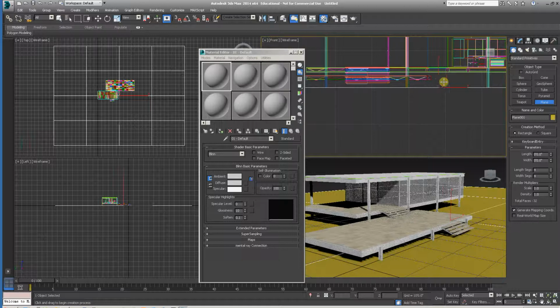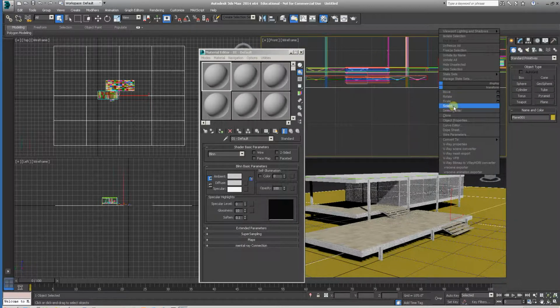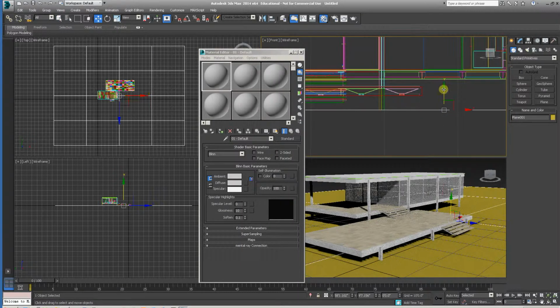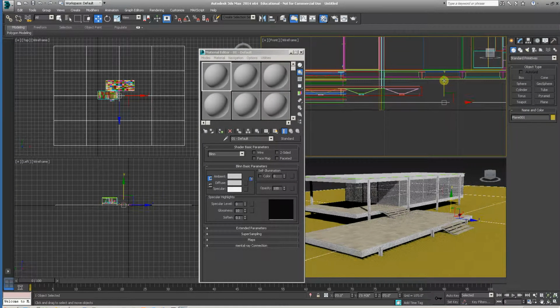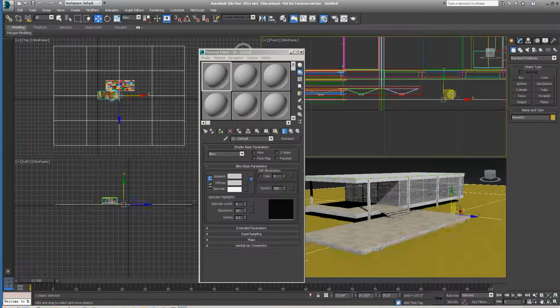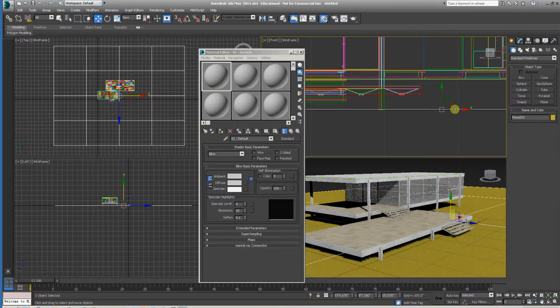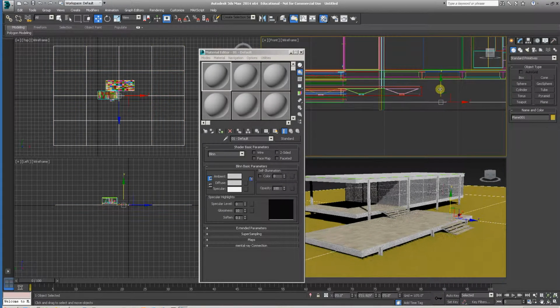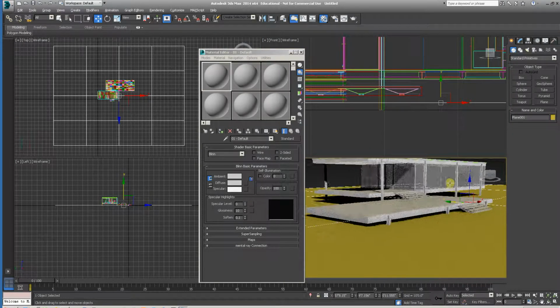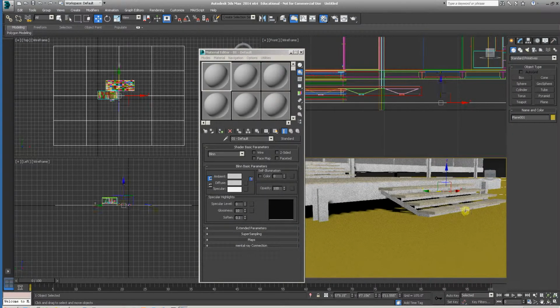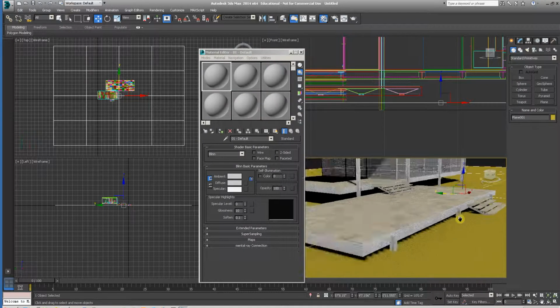Most of these objects have really nice right click menus, so if I right click over that, I can switch to move, rotate, scale, and a bunch of other options like hiding and unhiding. So I'm going to move this, and it has a gizmo that's very similar to the gumball in Rhino that will let you constrain moving up, left, or right, or within a plane, or constrained by individual axis. So I'm just going to move that plane up so it's underneath the first stair, and we don't have an unnecessary riser height for that first step from the ground.